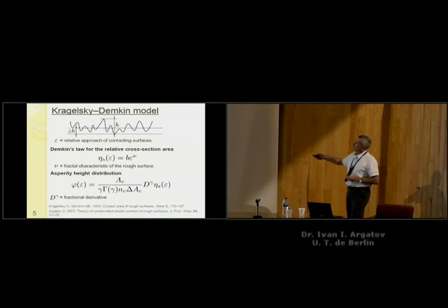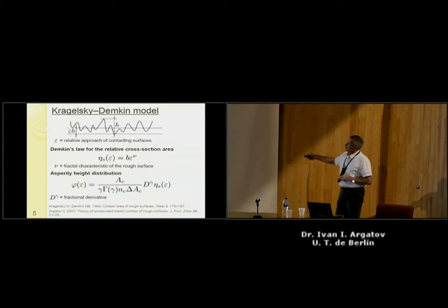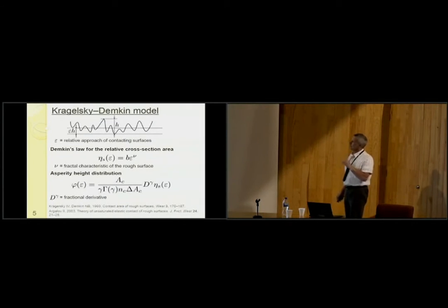A very important factor in this theory is the distribution of asperities. It is assumed that each asperity in contact is modeled based on Hertzian theory. And a very crucial consideration is that asperities do not interact between themselves.